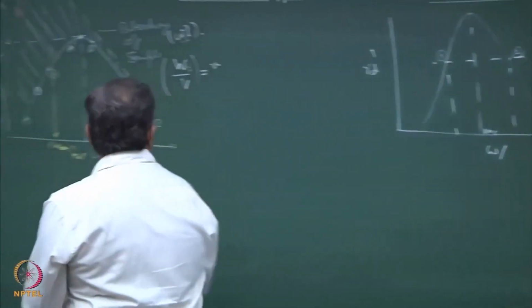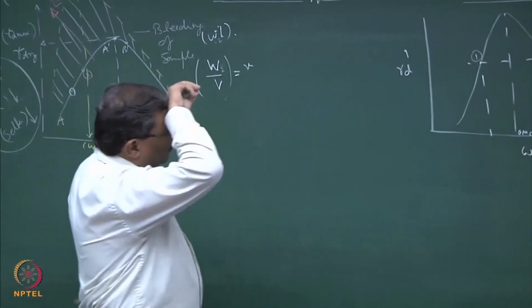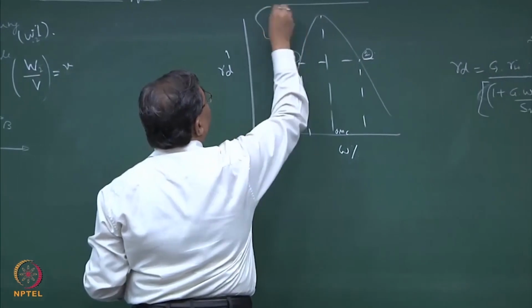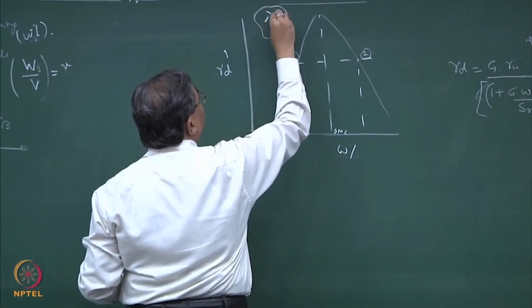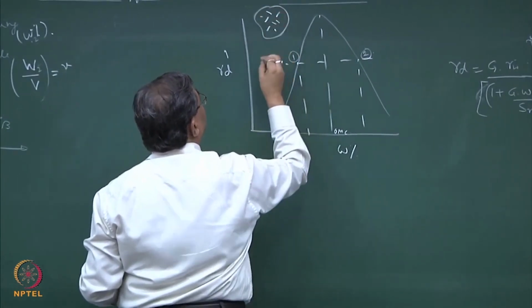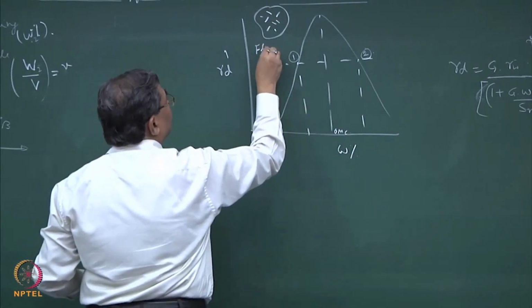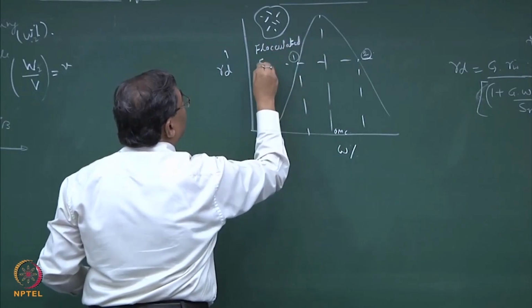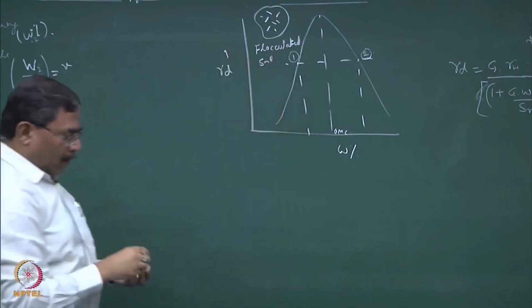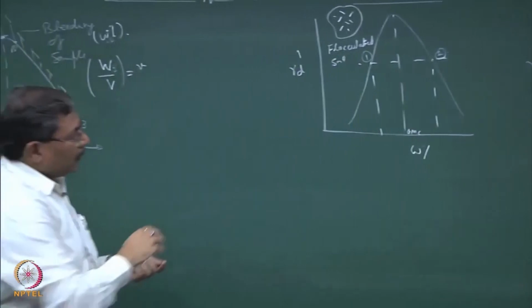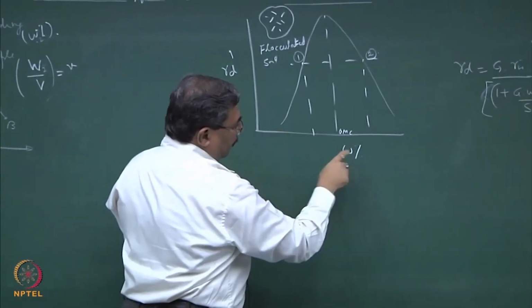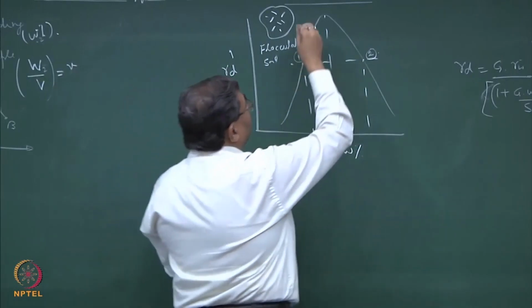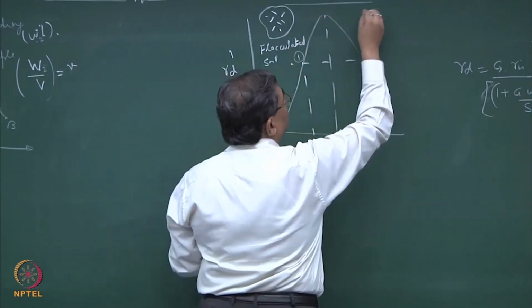The reason is, if you look into the microstructure which we have talked about, the grain structure of the soils, this side is a flocculated system. However, as you keep on imparting more and more energy, in the form of adding more moisture, this flocculated system gets converted to a dispersed state.